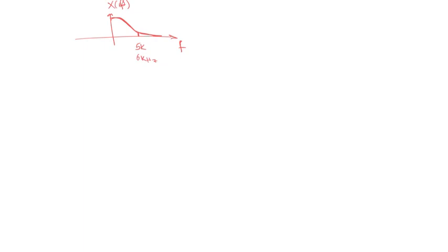Your project is a 3-band equalizer. What does this mean? It means that it should be able to take that frequency domain signal and divide that into 3 pieces. That spectrum that you see there should be divided into 3 pieces. And then for each of those pieces, you should be able to control its magnitude, increase or decrease it, which is what we call amplifying or attenuating the band, which is what you see in your equalizer as going to the plus side or the negative side, okay?